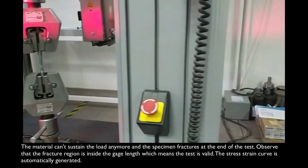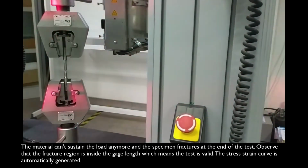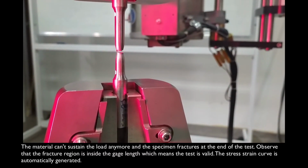The material can't sustain the load anymore and the specimen fractures at the end of the test. Observe that the fracture region is inside the gauge length, which means the test is valid. The stress-strain curve is automatically generated.